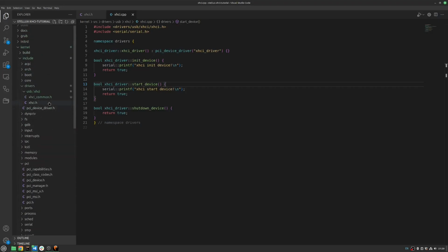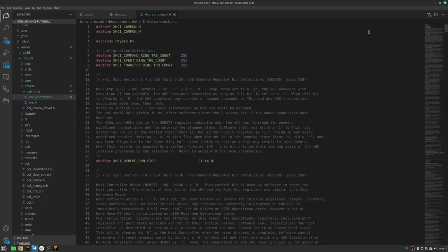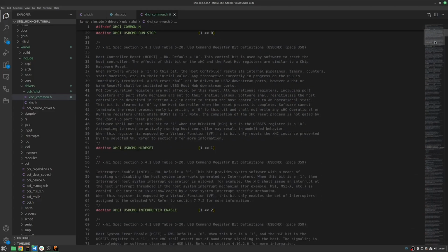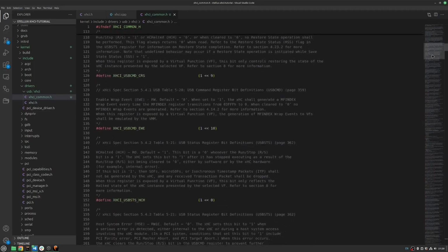Now in addition to those, before recording this video, I also added a file called xhci-common.h, which just contains a ton of useful macros, definitions, and above each one references to the official xHCI spec, section and page numbers, and explanations straight from the spec for each of the macros.